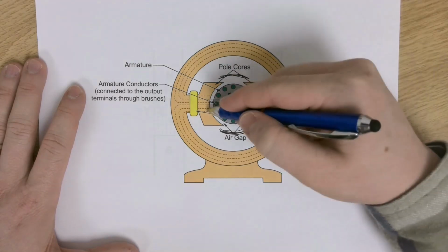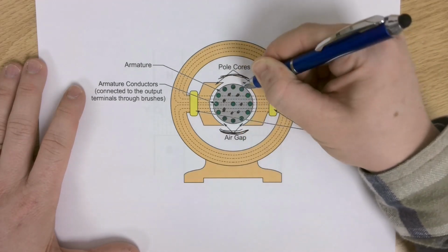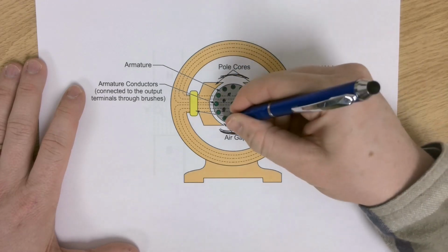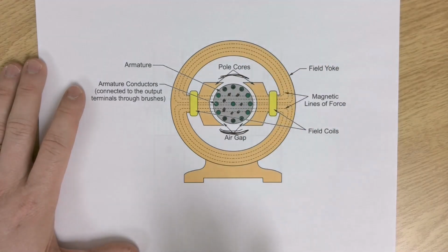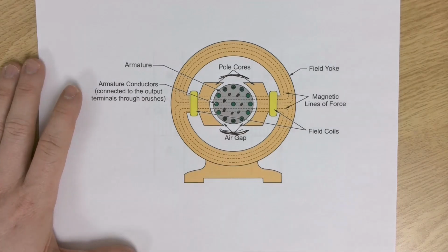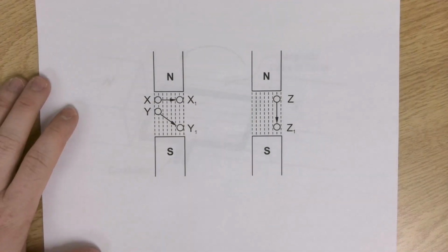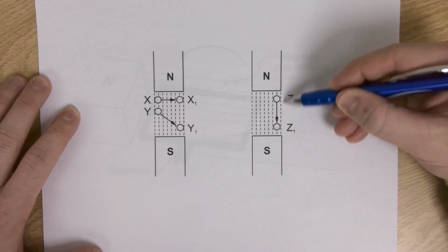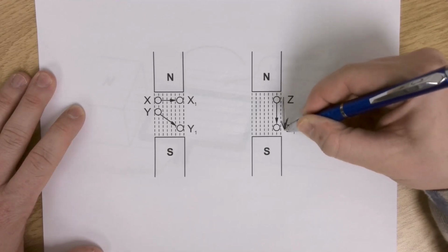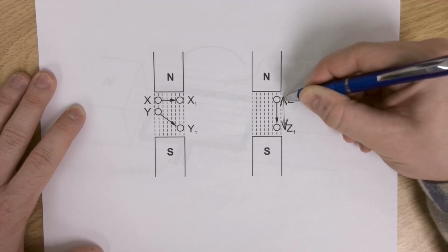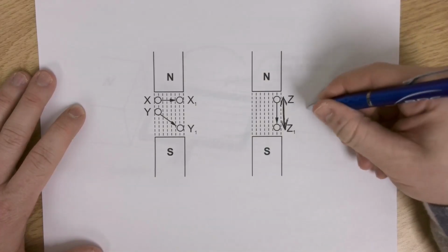Now, right now, with just these two pole cores, you can see down here maybe 6 of these armature conductors, also called armature windings, that are not cutting magnetic lines of flux at this very moment that we paused and cut this generator in half and took this snapshot in time. So once again, when we're not cutting magnetic lines of flux, either because there are no magnetic lines of flux, or because our conductor is exactly parallel with them, it's not going across them or interacting with them. So here, we're making 0 volts.